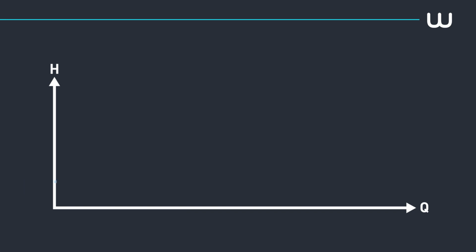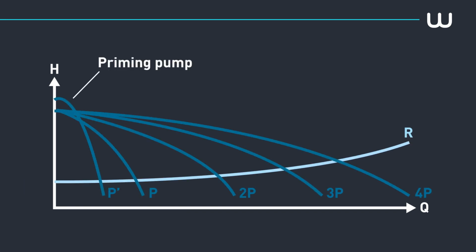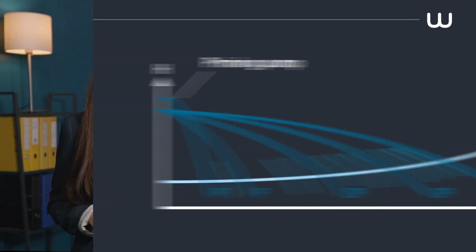Generally, a pumping station is fitted with several pumps working in parallel. Using a variable frequency drive on each pump provides for greater flexibility regarding the duty points, and therefore the discharge flow rate ranges, as can be seen in the following diagram. Let us now look at a few points that require attention if we wish to install a variable frequency drive in order to regulate a pump's operation.